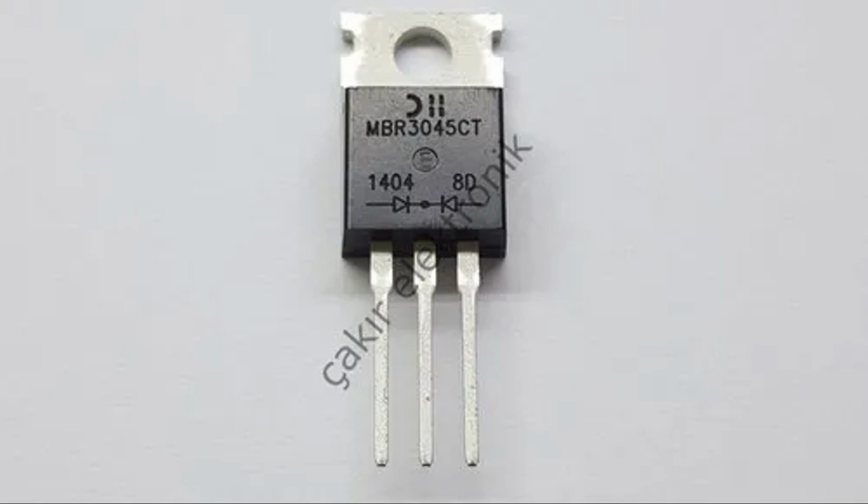Overall, the ability of diodes to quickly switch between conducting and non-conducting states is crucial in many electronic applications, particularly in high-frequency and power-sensitive circuits. Lower reverse recovery times are essential for improving the performance and efficiency of electronic devices and systems.